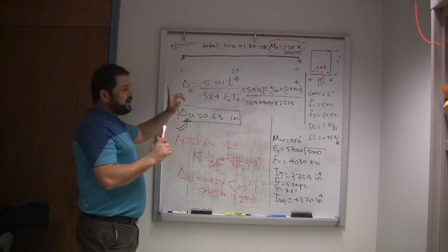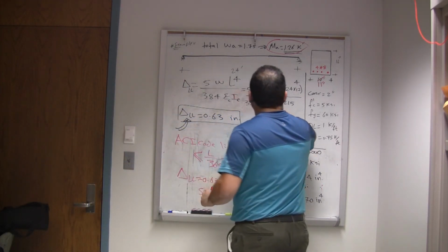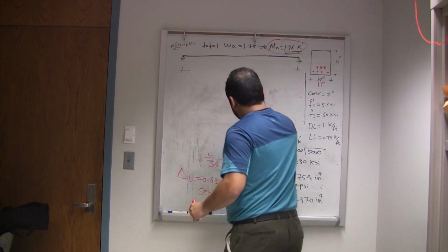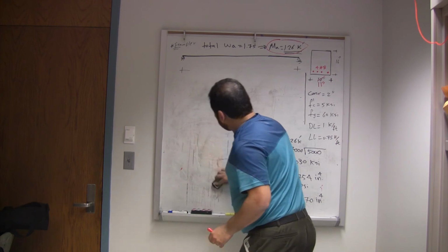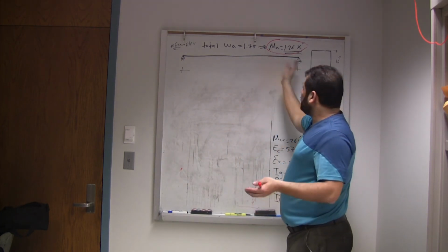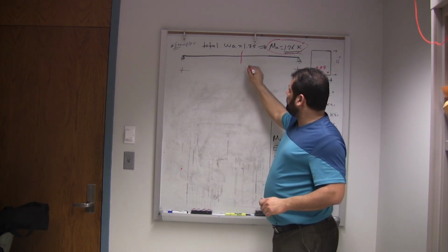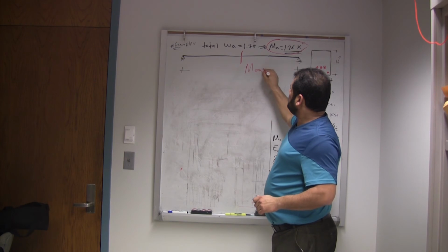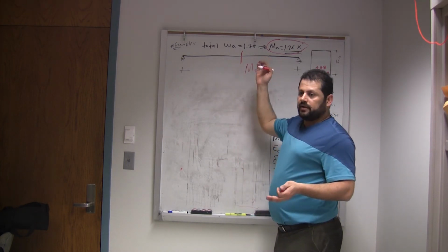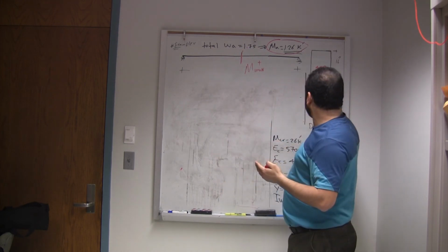Okay? There's one more thing I want to show you, which is part of the next topic, the development length or the cutoff points. Look. So how many bars did we need? We needed four number 8, right? Where do we need them? Here, at the maximum moment. This is the positive moment. At the maximum moment location, which was 173 kip-foot, that's how much we needed.